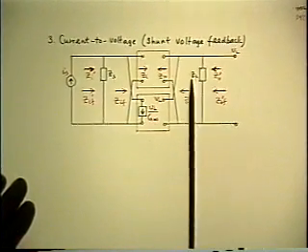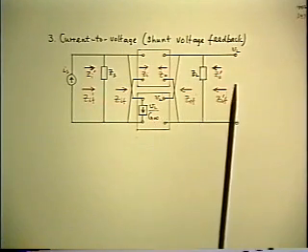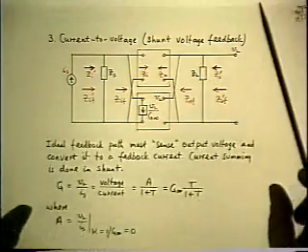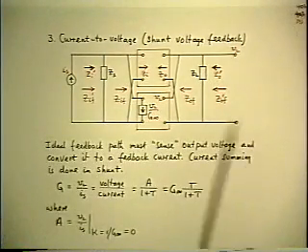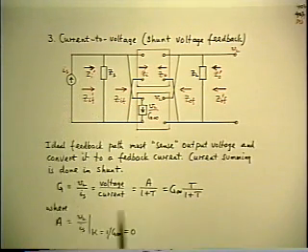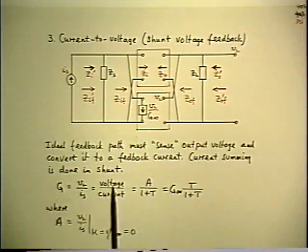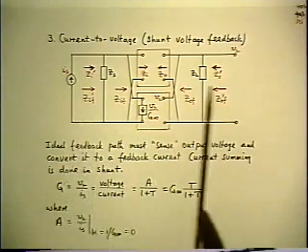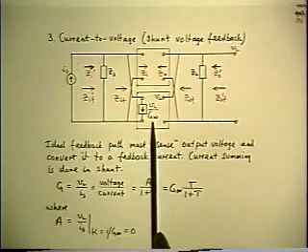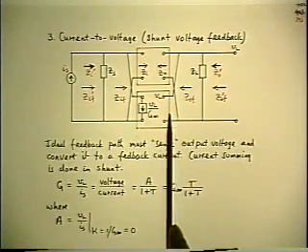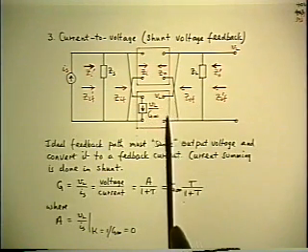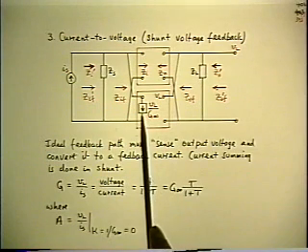So type 3 feedback, the output is back to the original configuration because the output signal is a voltage again. But this time the input signal is going to be a current instead of a voltage. So the requirement is G is a voltage over a current, namely a transimpedance. So the G infinity must be a transimpedance. So the K must be a transadmittance, upside down. So the K box has to sense the output voltage and convert it into a fed-back current.